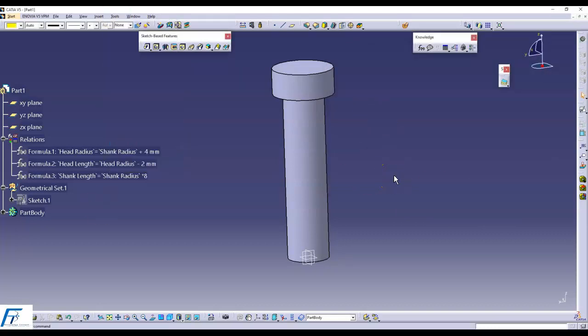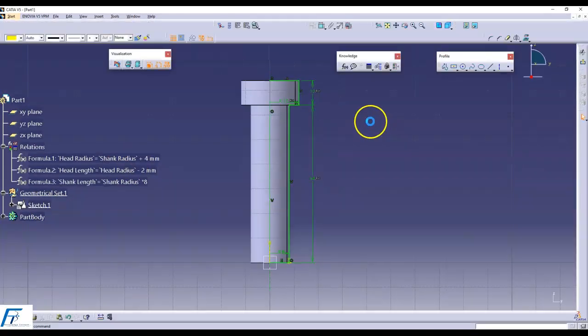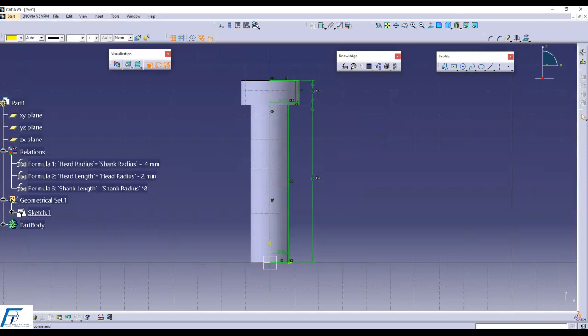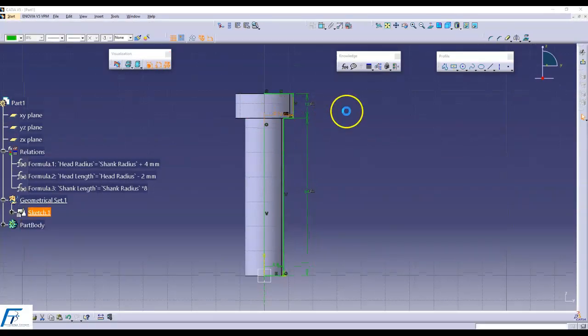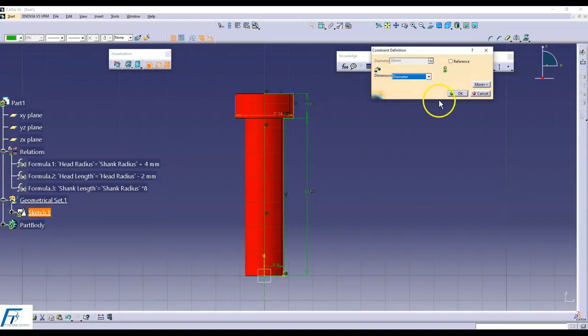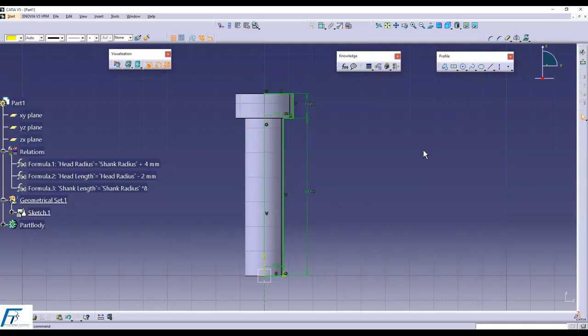So now, what is the biggest challenge? First, what we had as a challenge was renaming. I did that one. You understood how to rename it. And always remember, when you keep the values in terms of diameter, you cannot rename it. First important note, errors. What errors will come? You can't rename it when it is in diameter. I'll show you an example, okay? This is my component. That's the reason I just converted it into radius and renamed it.